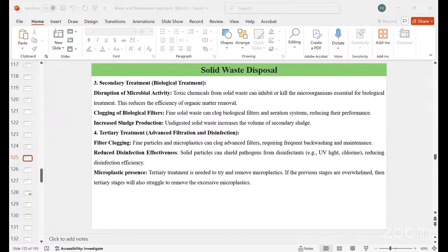So type 4. If you look into type 4, it is mainly human and animal remains, consisting of carcasses, organs, and some organic waste from hospitals, laboratories, animal pounds, and similar sources, containing about 85% moisture and 5% incombustible solids, and having a heating value of 555 kilocalories per kg as fired.